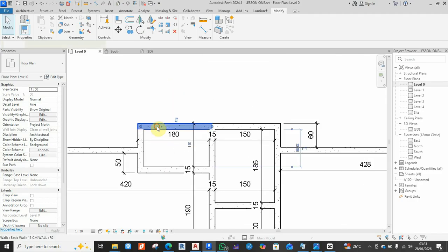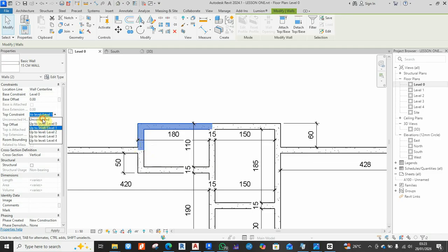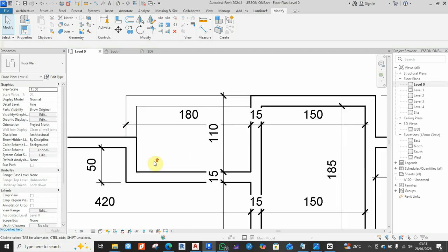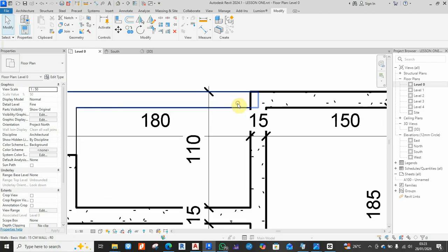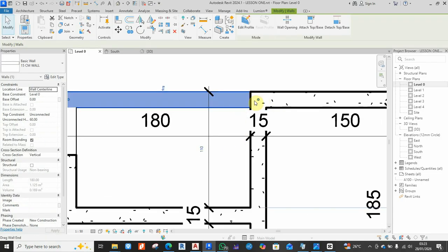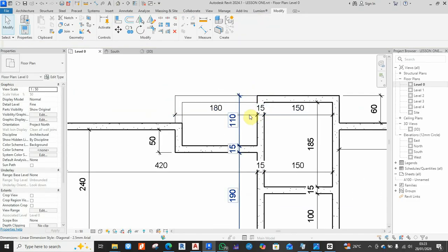Now let's come to this. We are going to select this wall, hold the control key and select this guy, and then come here to level 1, upper level, and click on connected and give 60. Here is fine, here is also fine. Somehow if you click here, you will see that this wall is going in here. I want to click here and bring it right out here like this. I like it that way.